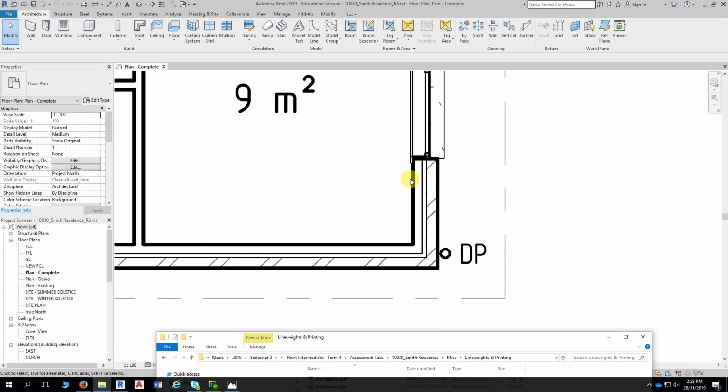Now, I'm going back to, I guess, when I was using and teaching AutoCAD. We used to thicken up the lines of the masonry walls, so they were thicker than the line work of the timber walls inside, given that this is brick veneer. And we talk about line thicknesses being 0.15, 0.18, 0.25, 0.35, 0.5 and 0.7.